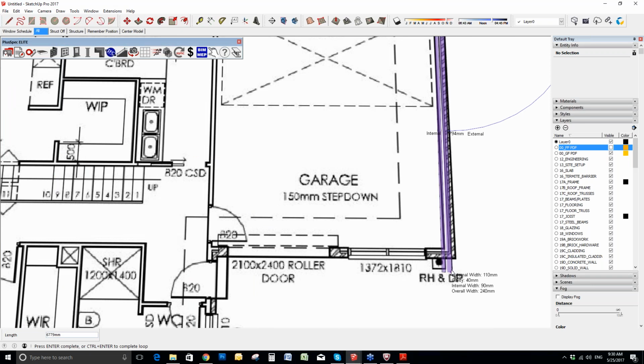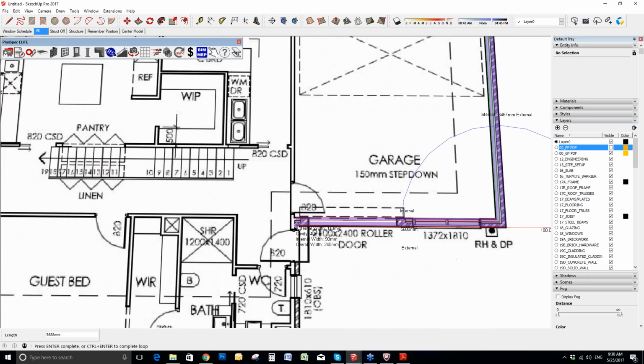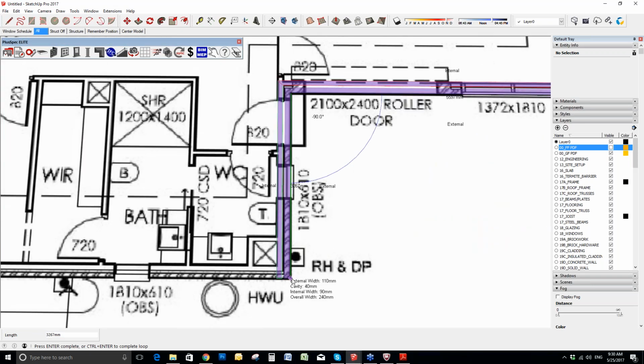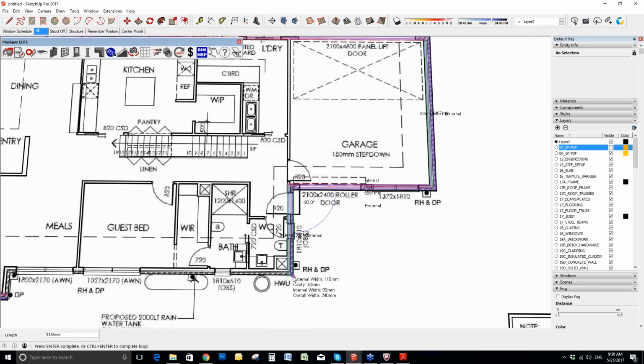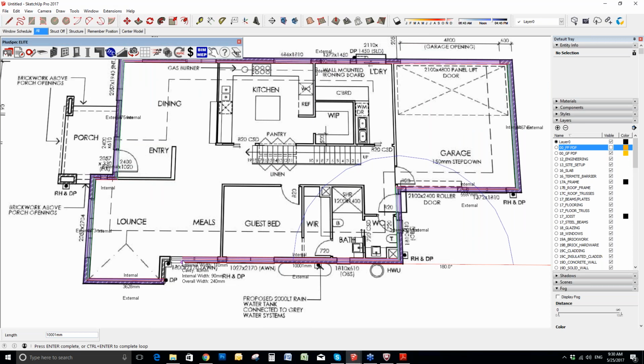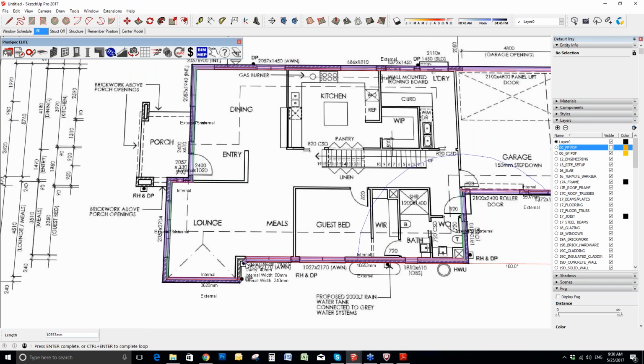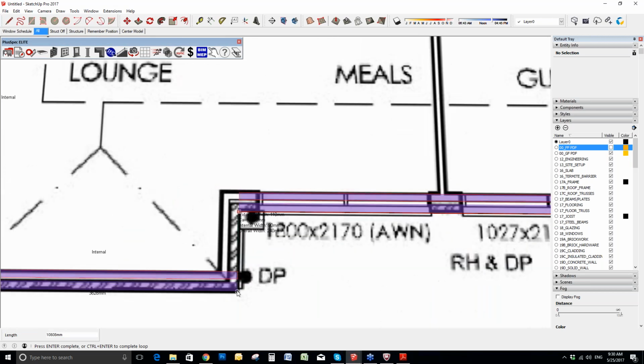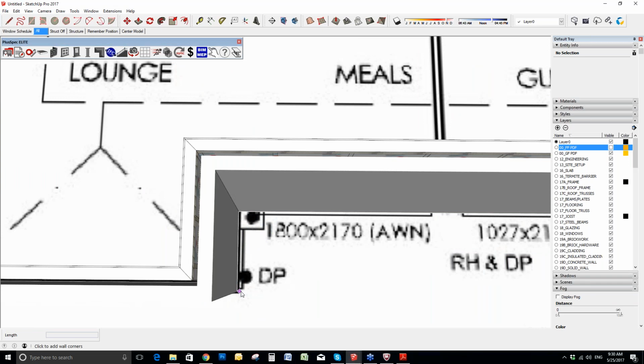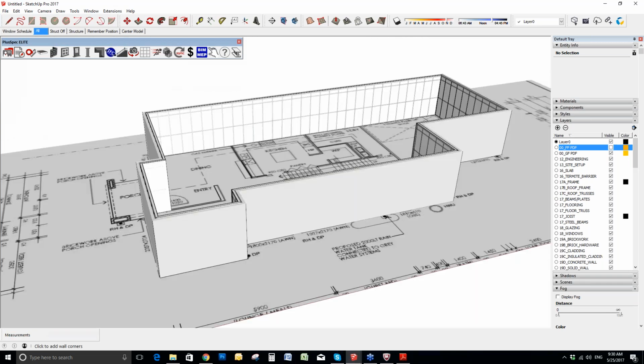I'm looking simply at the red and the green, making sure that my wall is reading as green and red. Now, the last joining piece is the one you want to be aware of, because to easily reference the first point so it's exactly at 90 degrees, you want to hold down shift. Then you can hover over the starting point, which will turn to that black circle. Left click it, and now you're going to come down exactly at 90 degrees, and you can simply form your walls.